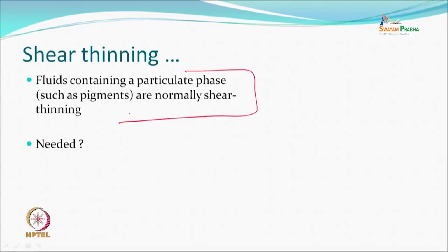Yes, we do require shear thinning, because the time taken for even the smallest droplet to come out of the nozzle is very, very small, and therefore the shear rate is very high. If it is not there, back pressure will develop, the actuators may not work very nicely, they may be adversely affected, and the functions may be badly affected. And so, we do require shear thinning behavior of the inks for printing.